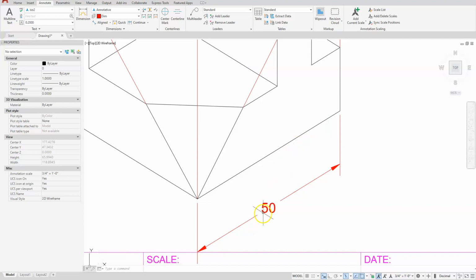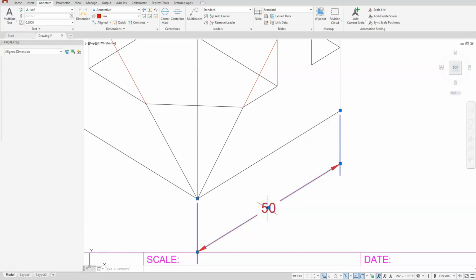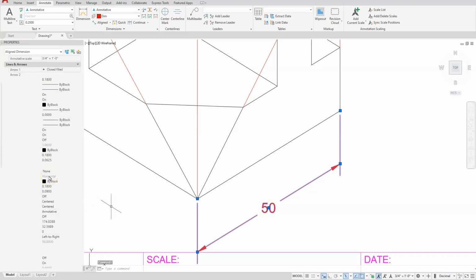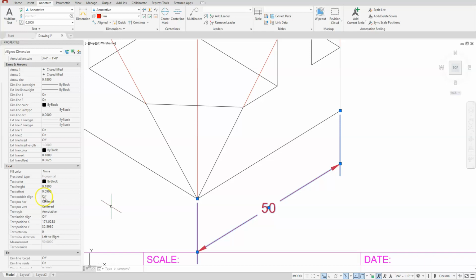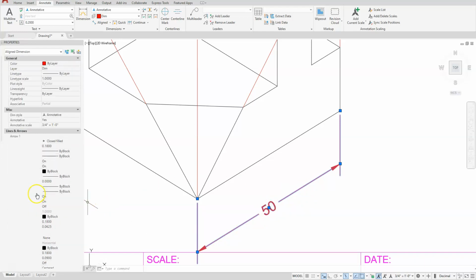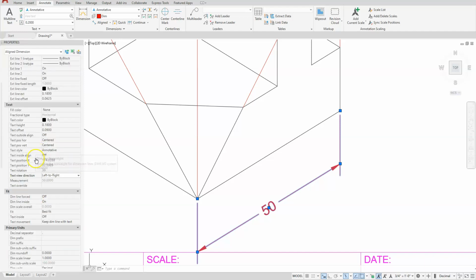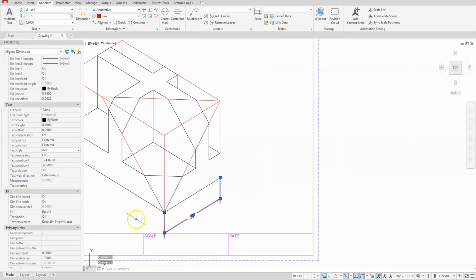As for the text, select your text. Come to where it says text rotation angle. And with this one, you're either going to set it to 30 or -30. I'll try 30 first. And now you see that it's rotated that direction. And then I'll scroll back down to the fit one. And then I'm going to choose either ISO 1 or ISO 2 underneath my text style. You can see that ISO 1 is the one that I'm going to need to stand this up. Now you have your text standing up.